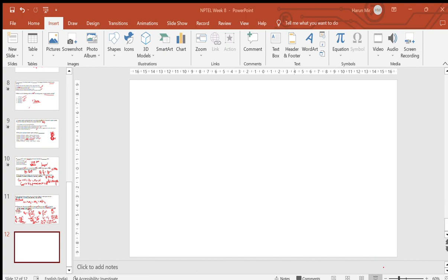It's correct. So this says that the mass flow in this particular problem, when you have the same volume for two types of mold, and you have kept the length of your cylinder equal to the length of your rectangle, then the mass flow rate will be higher in your rectangular mold as compared to your cylindrical mold, right? So the type of your mold will depend largely on your geometry. The mass flow rate will highly depend on your geometry of the mold.